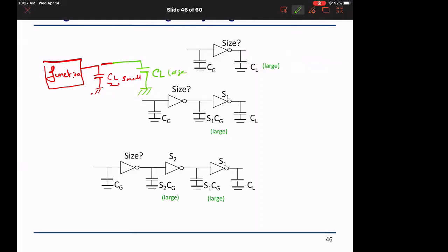I cannot go back and tell the designers to fix and optimize the ALU, because this is a module that has to be shared, used everywhere, and needs to be compact. So facing large wires, what we typically do is insert buffers, meaning we help the function by inserting buffers to be able to drive this large wire.